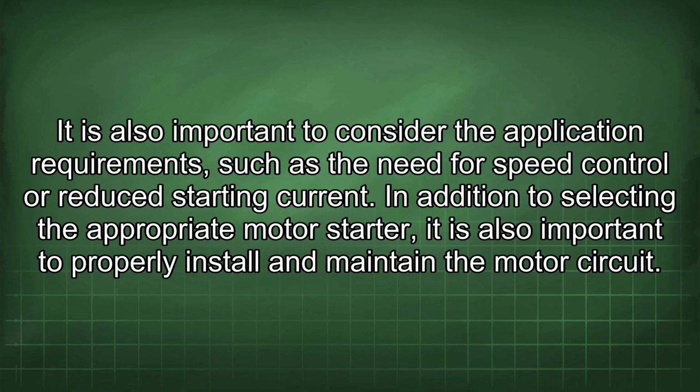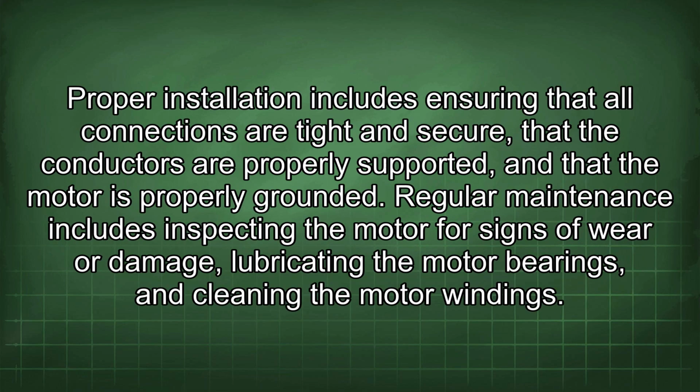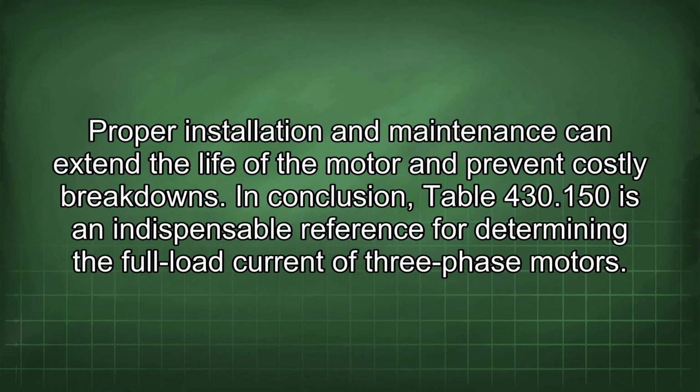In addition to selecting the appropriate motor starter, it is also important to properly install and maintain the motor circuit. Proper installation includes ensuring that all connections are tight and secure, that the conductors are properly supported, and that the motor is properly grounded. Regular maintenance includes inspecting the motor for signs of wear or damage, lubricating the motor bearings, and cleaning the motor windings. Proper installation and maintenance can extend the life of the motor and prevent costly breakdowns.